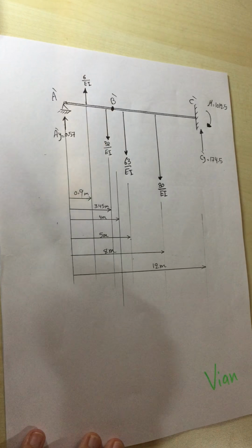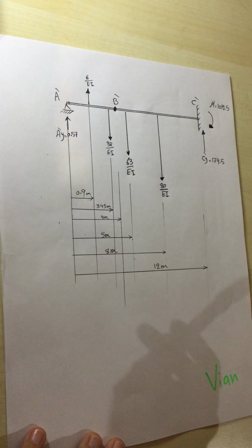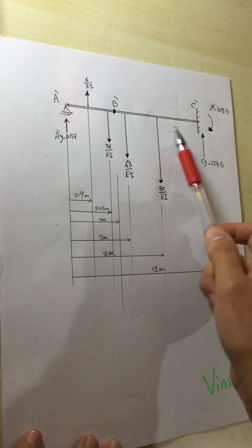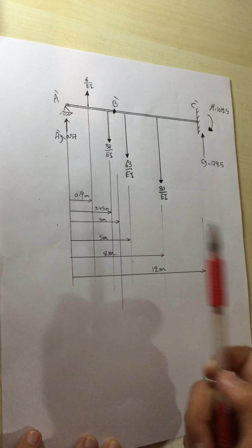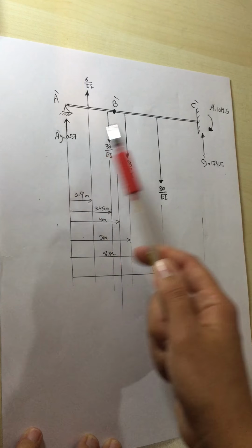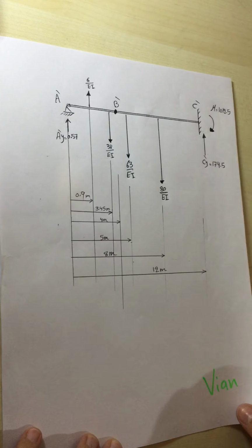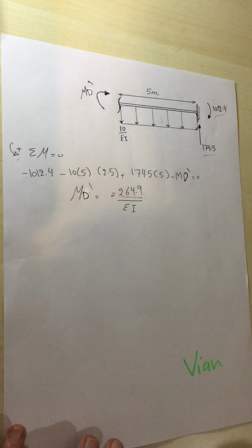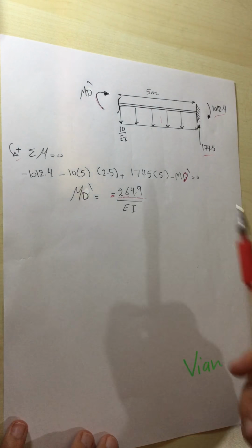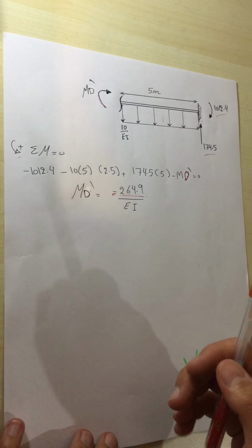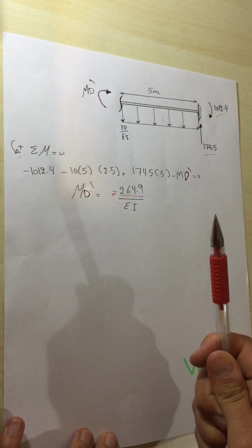And then these whole concentrated loads, I'll transfer them onto the conjugate beam itself by their distances, so I can determine the reactions at A dash and C dash for the moment and vertical forces. Finally, now I can determine the deflection at D dash, which makes the moment.